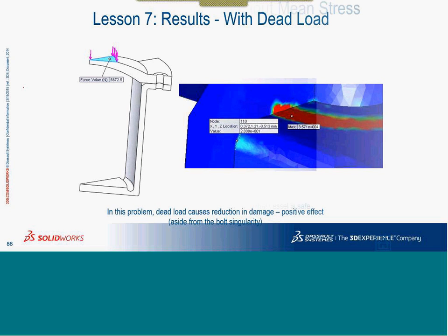And secondly, one interesting topic which I will try to cover, but it is more towards dead load. Even if the load is repetitive, in most analyses there will be at least a few different things, or it is as simple as the pressure created by a bolt. This pressure is not changing, it remains constant throughout, and it is called a dead load. That adds to the overall stress or the amplitude of the stress, but not in a repetitive manner, it is just offsetting the stress level. And there are examples in this setup by which you can understand how to simulate that.